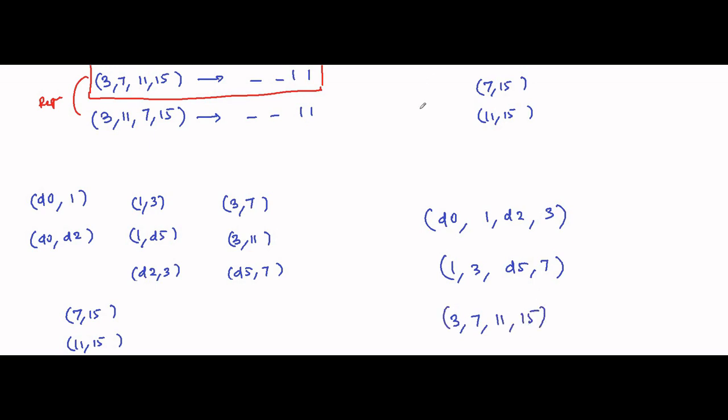Okay, so now again our objective is to find out whether the minterms that are present in these minterm pairs are already present in the merged minterm pairs. If they are present, we will cancel them, we'll eliminate them because they are redundant minterm pairs. Because in the essential prime implicants, the final minimized Boolean expression, we don't want any redundant or repeated minterms or minterm pairs. So here D0, 1 is present here, 1, 3 present here also, 3, 7